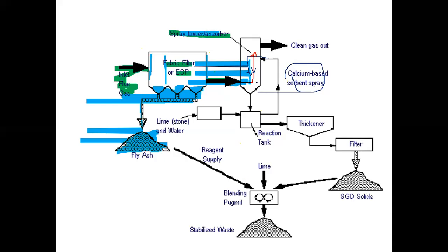Especially SOx are dissolved. Then at the top of the absorber, we can get clean gas, especially SOx-free gas. Carbon dioxide is slightly soluble in water, so we can remove some percentage of carbon dioxide also. Now we get clean gas out. We can release this gas to the atmosphere by sending it through a tall chimney or tall stack.